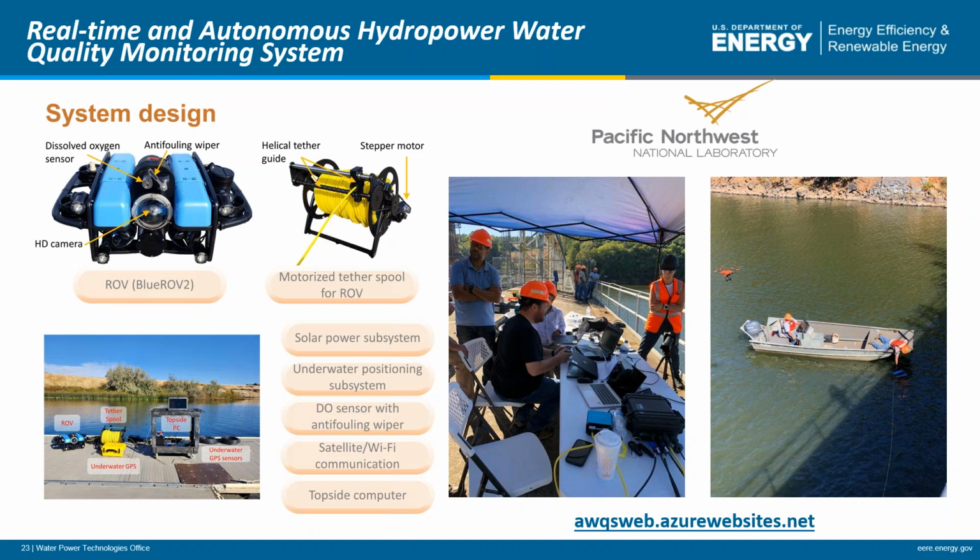And so this will allow measuring a complete dissolved oxygen profile in several different dimensions in both a forebay and, most importantly, in the tailwater or afterbay, which those of you who have ever been in a boat below an operating hydro project know the dangers involved there. So this will use, as I said, a robotic system to give you a better look at the dissolved oxygen system, not at one single point, but throughout the water column. So why is that important, and what is the unique application here?